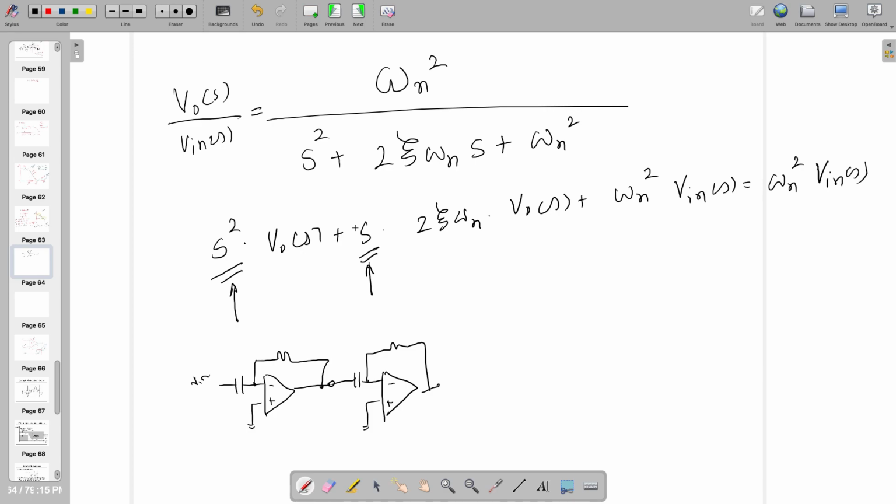And we also studied that if you have to find the value of R and C, the ratio has to be kept in such a way that R has to be a very high value just to make sure that it will not load the output, right? And capacitor has to be low, preferably in the range of microfarad, and this one may be in the range of 100 kilo ohms, right? So you can make the circuit using op amp if you know the transfer function.